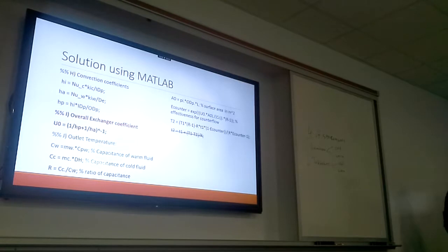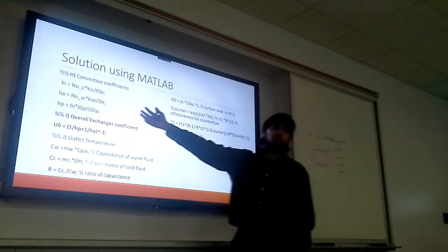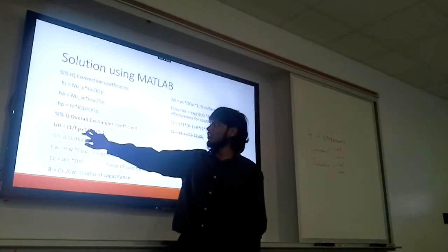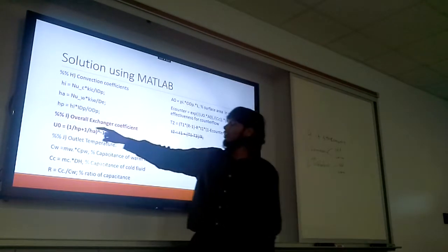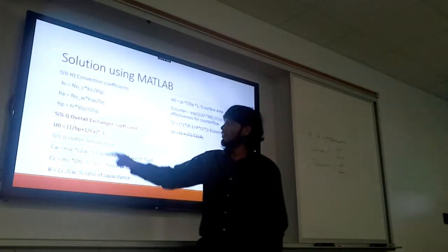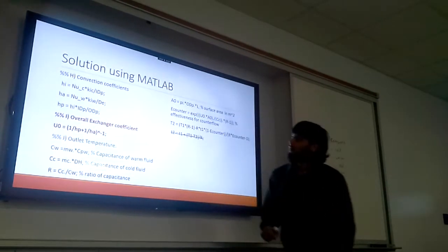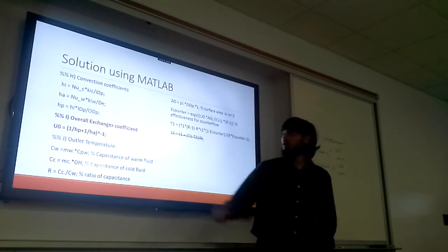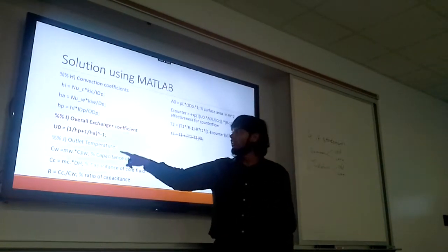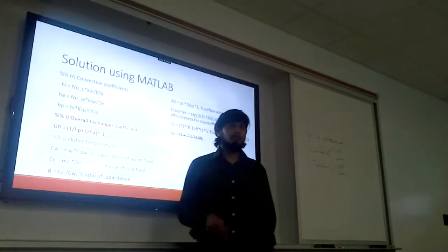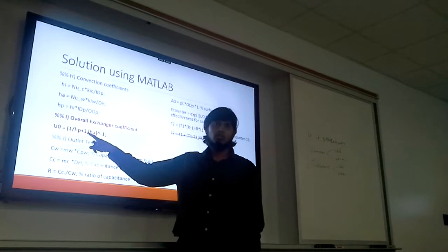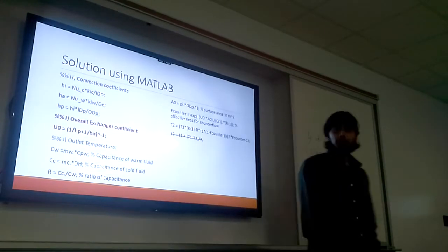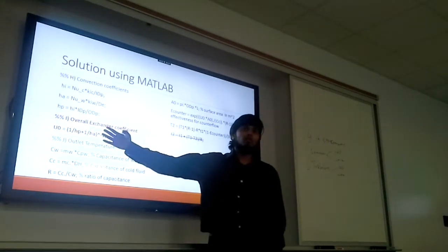And then based on the Nusselt number, as was mentioned, you can find the convection coefficients. You find the three convection coefficients. In this case, you only end up using two of them because the inner tube coefficient is actually a function of the h sub i. And so one of the solutions that we wanted to find is the overall heat exchanger coefficient. In this case, it's going to be 1 over hp plus 1 over ha. The ha is the annulus convection coefficient, and the hp is the inner tubing coefficient. Okay, and then so you have one solution. So we've taken down one.